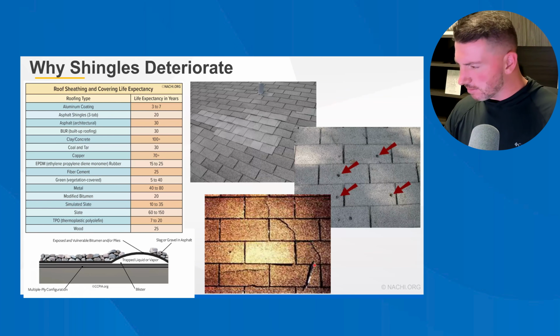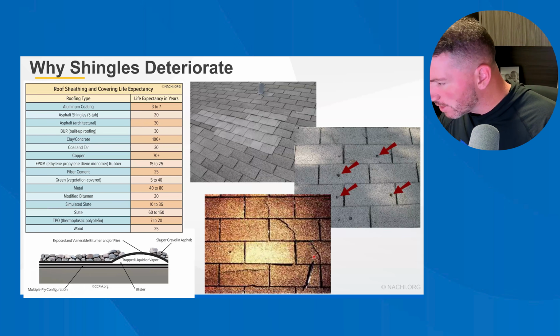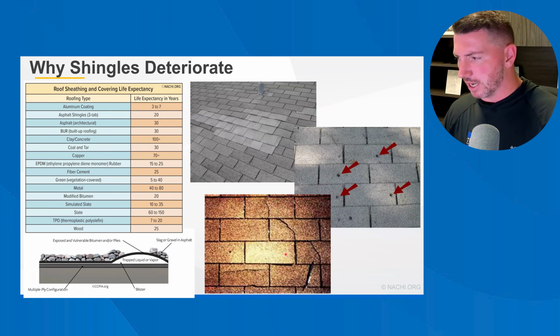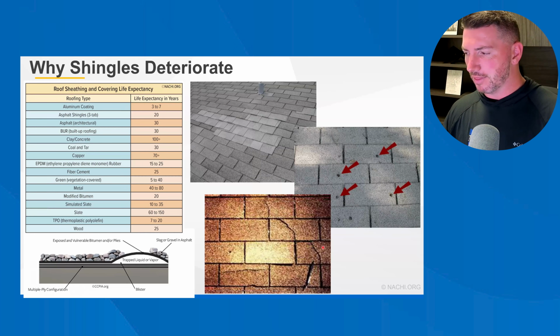Then this split here is, sorry, this is a full shingle under here, and then this next one gets installed on top. And so basically, this shingle is a full shingle, this shingle is a full shingle. This is a 6-inch overlap of one shingle, and same thing here, where when these two expand and contract and are trying to separate and pull away from each other, this shingle is fastened to both of them, or not fastened, it's sealed to both of them because of the sealant strip. And so you got this fighting against this, it splits this, and it's happening a lot in this roof.